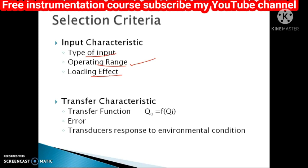The next is the transfer characteristics, which consist of the transfer function, the different errors, and the transducer's response to environmental conditions. Let's start with the transfer function. The transfer function of a transducer is a relationship between input and output quantities. Let Q0 be the output quantity and Qi be the input quantity.